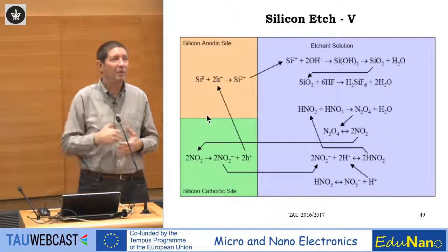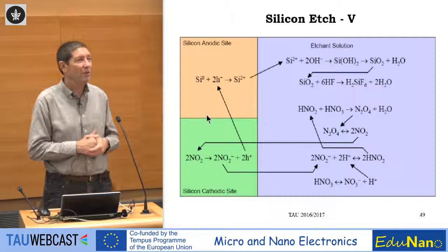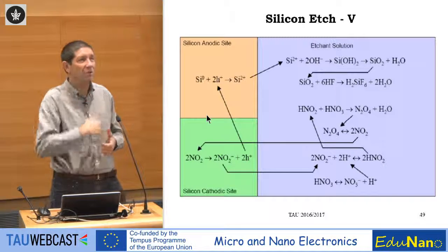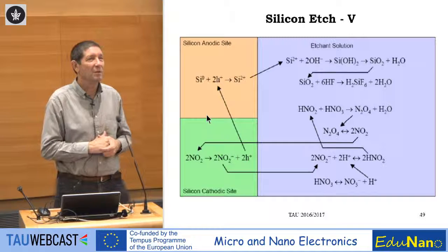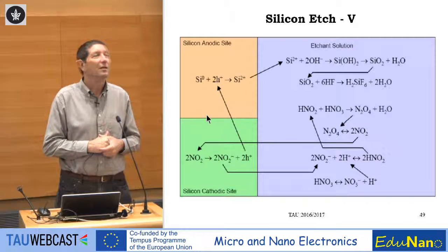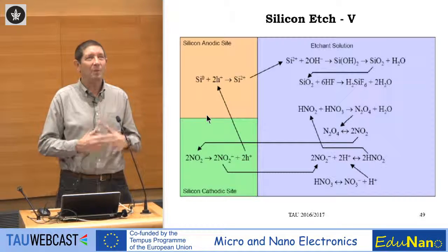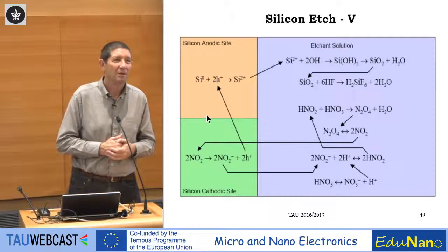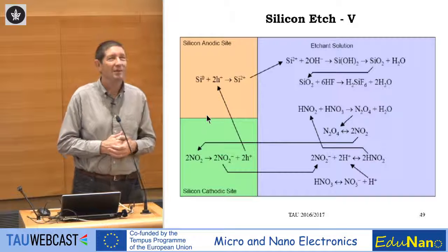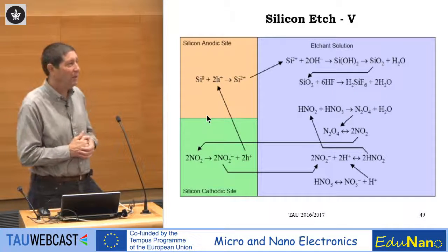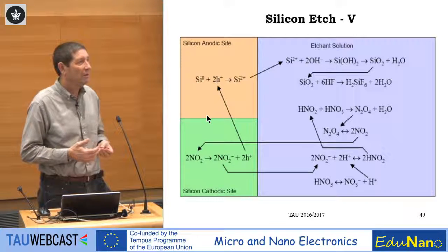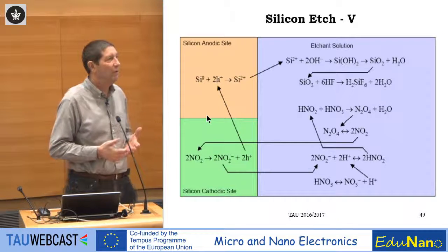Another way: if I don't have doping and I want to accelerate, or current, but I cannot touch the wafer, I cannot supply current, what? Let's say I don't have a power supply, I'm in the middle of an island, there's a lot of sun but no electric fields. Light. If I illuminate the substrates, I can generate electrons and holes. They can also modify etching rates.